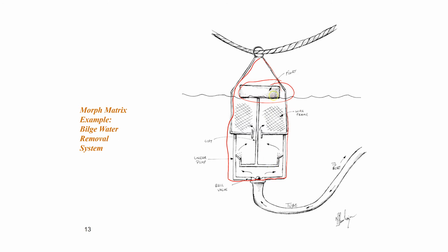So you get relative motion between this float and the attached piston in the body of the pump. And so this again is a lift pump, and so when it rises, water is sucked in behind it, and when it falls, the water is allowed to come through by way of these valves to this side. So it also looks kind of like a bicycle pump if you've ever taken one of those apart before.